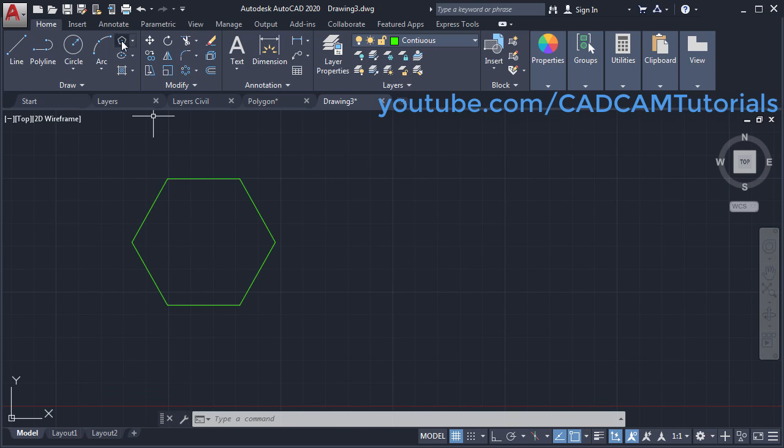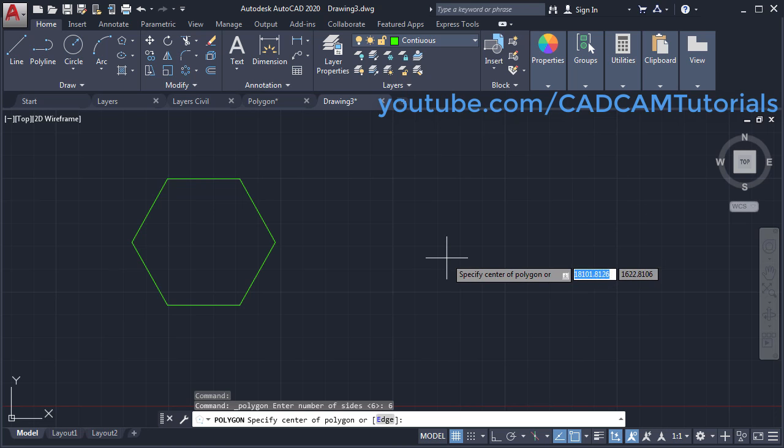Again click on polygon. Then specify number of sides. Again I will give 6. Enter. Then give the center point.